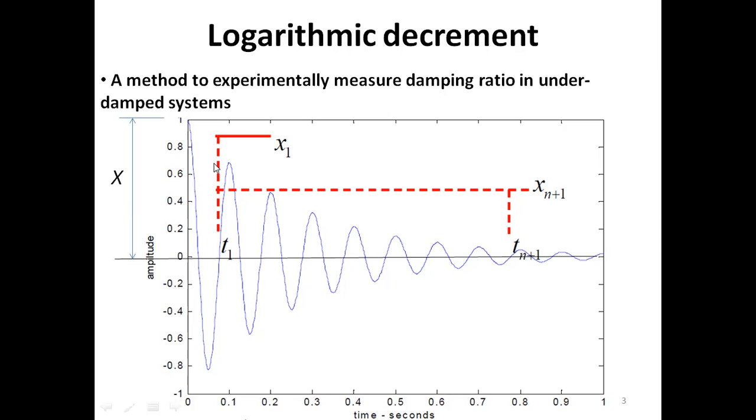And you could see that as the time passes, the displacement slowly and gradually decreases. In other words, the amplitude of the displacement is decreasing. So what does that mean? It means that our system has gone through a vibration. So our system is actually an underdamped system.